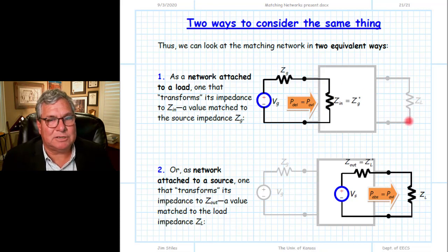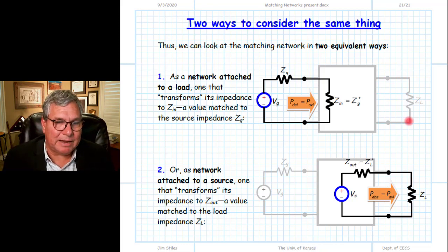Make sure you understand how that all fits together. This is very important in this class: once you have one thing, a string of things happen. Now again, one more warning, and listen to this. This is true if this two-port network is a lossless matching network. Not just a lossless network. Most lossless networks are not a matching network. Most lossless networks are not going to solve those design equations. So it's not enough to have a lossless network there.